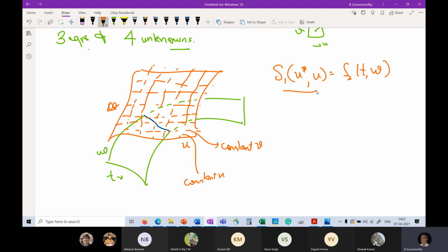Right? So I have a curve and a surface, and I can find the intersection of that. And I'm going to, let's say, circle it here. I get this intersection point, I get another intersection point, one intersection point here, one intersection point here, and okay, those are the intersection points. Because the result of this is a point, right? When I intersect a curve with a surface, what will I get? I'll get values of U star, V star, T star, and W star as a solution. Right? So this U star and V star will give me the point on this surface, and then T star, W star on this surface will give me the same point, and therefore that's my point of intersection. The red and blue dots are my points of intersection.